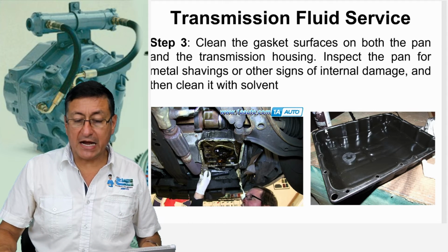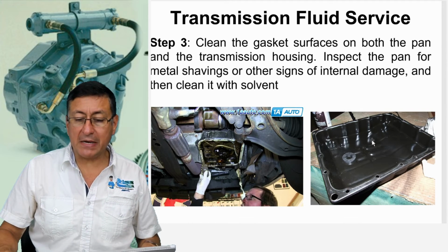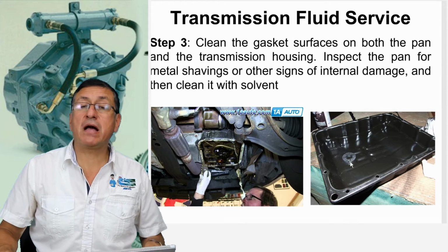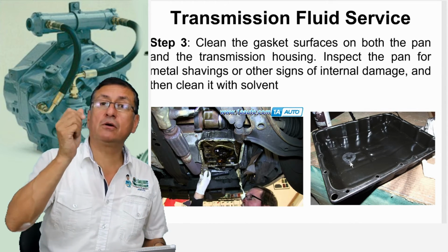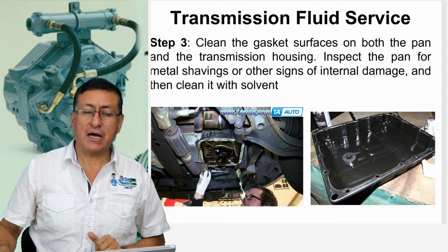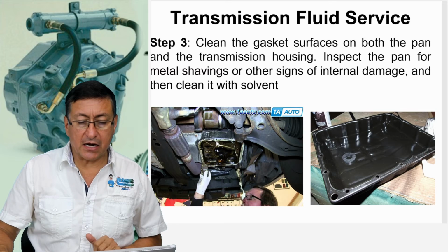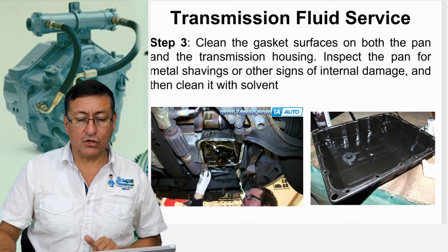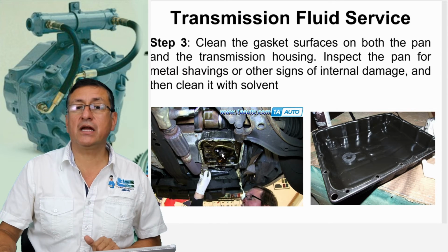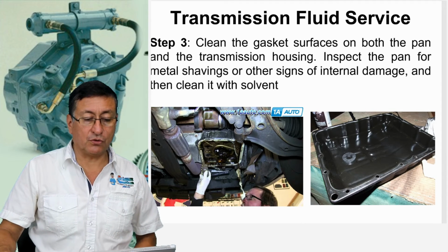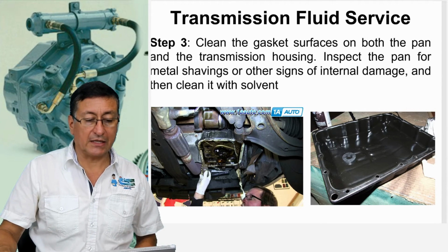You need to remove the gasket of the oil pan. Clean the oil pan. This is the magnet. Remove the magnet. Remove the particles, the iron particles on the magnet. And in this area, remove carefully the old gasket, and clean that area. Don't touch this area. In this area you have the computer and the filter. Right now we are going to explain the procedure to verify that.